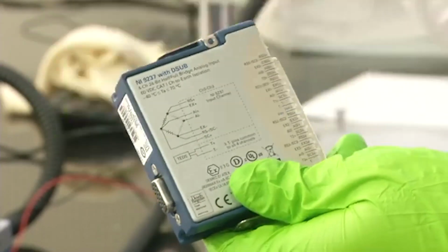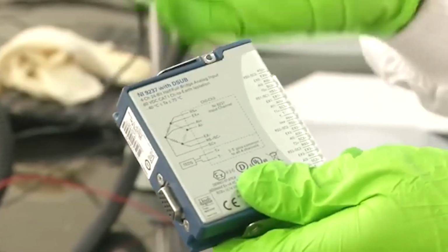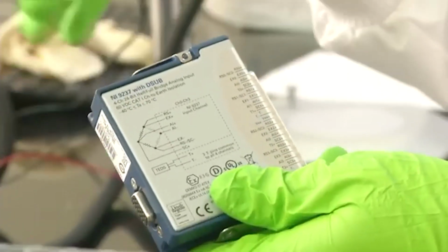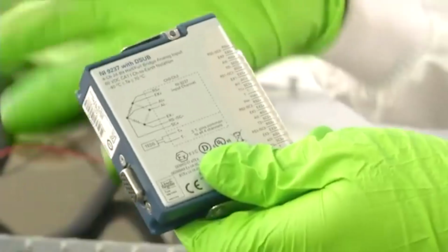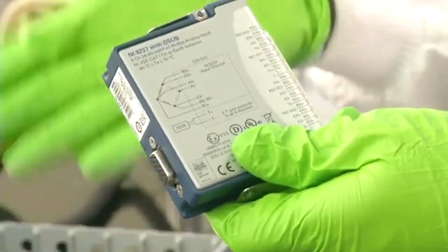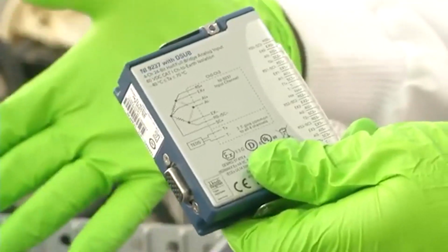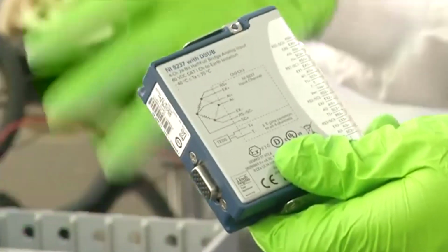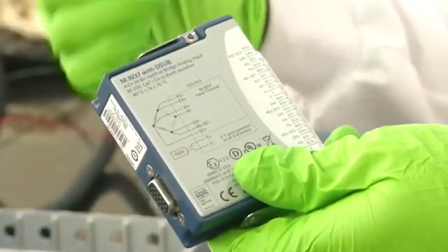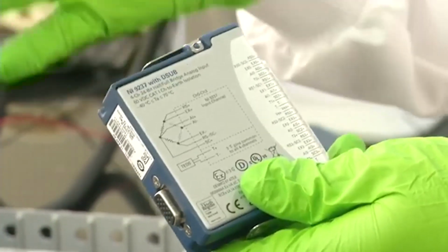In case we are dealing with force sensors or strain gauge based force measurement units, since these are resistive types of sensors, you need to convert your resistance change to a voltage output. One way to do this is either a half bridge connection or a full bridge connection. A full bridge connection will always have very good sensitivity as well as much less linearity error when compared to a half bridge.